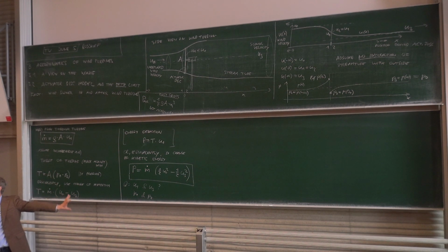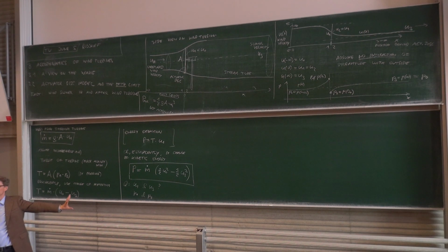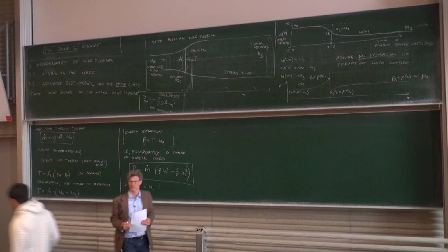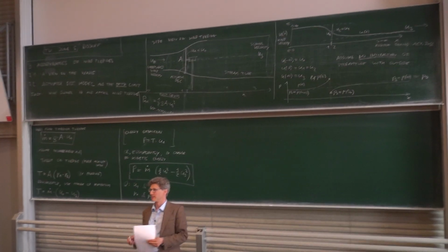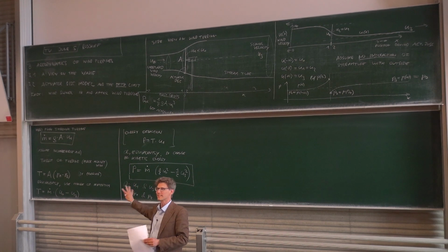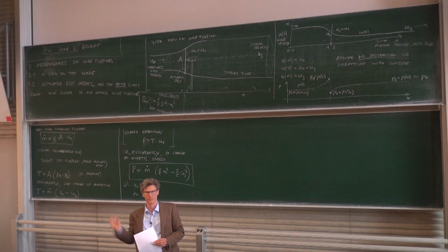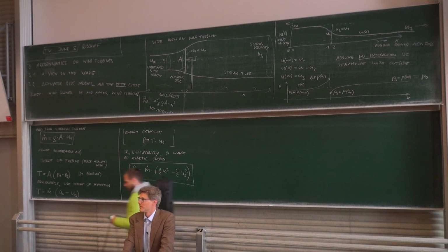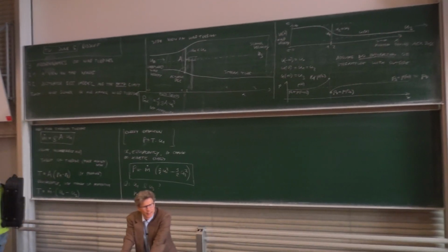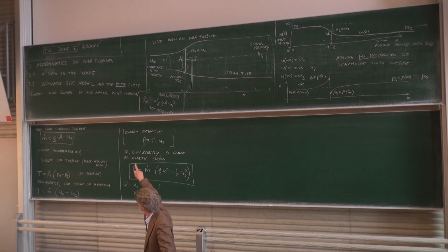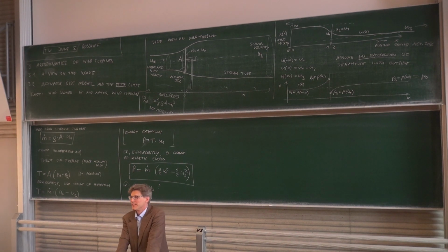And what will help us in order to derive them is one extra physical principle that I will not derive now, and that's called Bernoulli's principle, and it's part of one of your questions. So we need Bernoulli in order to get the extra equation that makes it possible to collect everything. But that's basically now the picture, and next time, I think next Tuesday, we will finish the actuator disk model and derive Betz law.